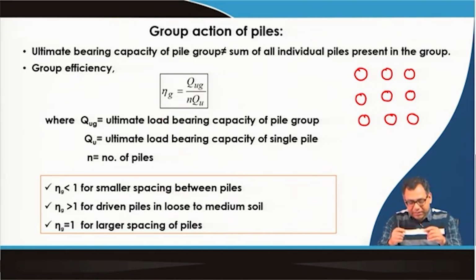So, that increment will be more for the group, because here the soil will be in the confined condition. When you apply the driven pile, the surrounding soils within the group will be compacted. So, the strength will increase, and the efficiency will increase.